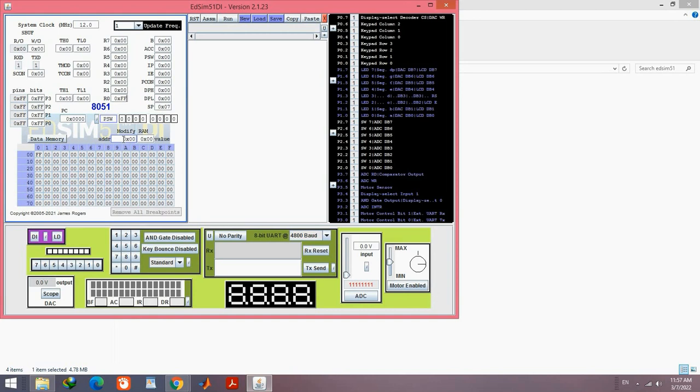So again, if you want to initialize the content of the memory manually, you can use this part. This is the address and this is the value. For example, I'm going to put in address 30 hex a value AB. So the address is 0x30, and the value that I'm going to add here is 0xAB, or AB hex. As you can see, AB hex is entered in address 30 hex.